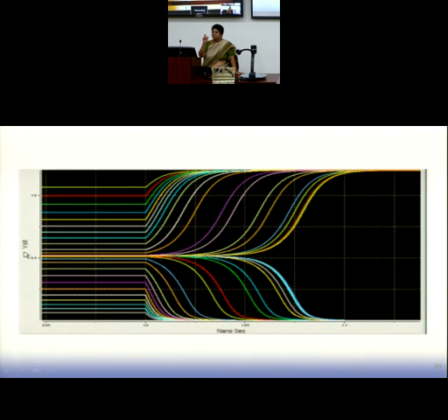Remember, the range of metastability, which is between t setup and t hold, coincides with the range VIL to VIH of my bistable element. It coincides with that range, VIL to VIH of my inverter, because only in that range it is in a transition state.